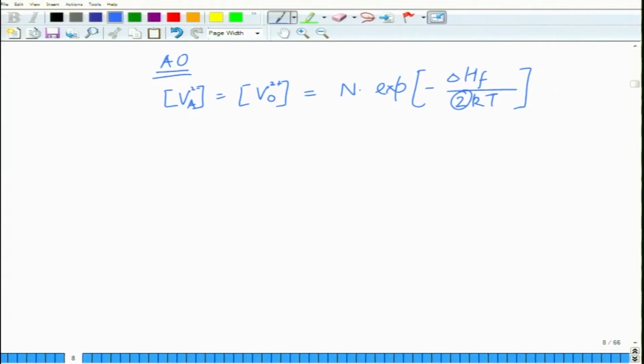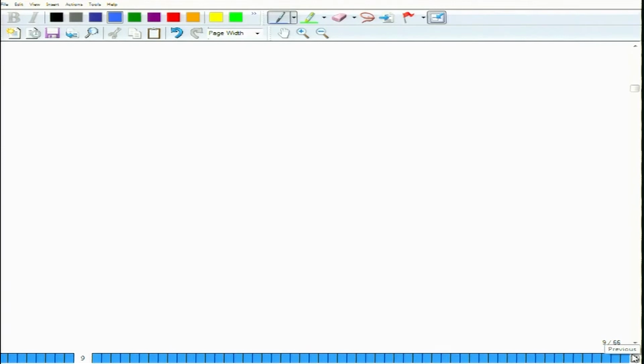So, this is about the point defects discussion: you have point defects such as vacancies and interstitials, and point defects are basically stable, equilibrium defects, and free energy is minimum at a certain concentration at a given temperature, and their concentration increases as a function of temperature. As you increase the temperature, they become more in number exponentially. Okay. Now let us discuss the second category of defects, which is called line defects.